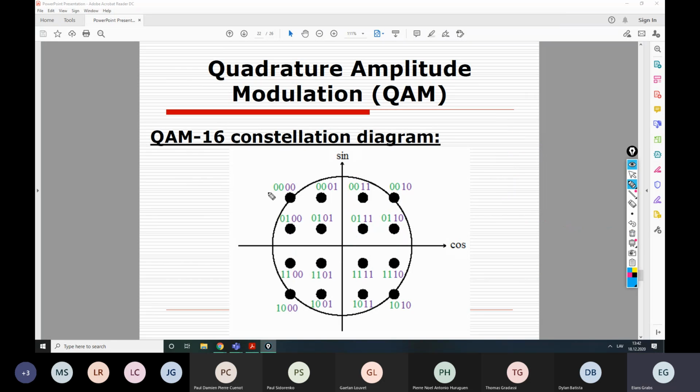But another thing you need to see here is that we are still using gray coding between these neighbors, right? If we watch horizontally or vertically, the neighbor symbol pairs differ only in 1 bit in any possible way, right? So you will not find any pair in this picture which is near to each other, and we look at the direction of either horizontal or vertical. We are not considering diagonal direction because that distance is greater than these short distances, right? So we only take into account the shortest distance symbols. And that's why actually this is the best possible arrangement of the signals, because in this case we can provide actually equivalent distances between each symbol, right?